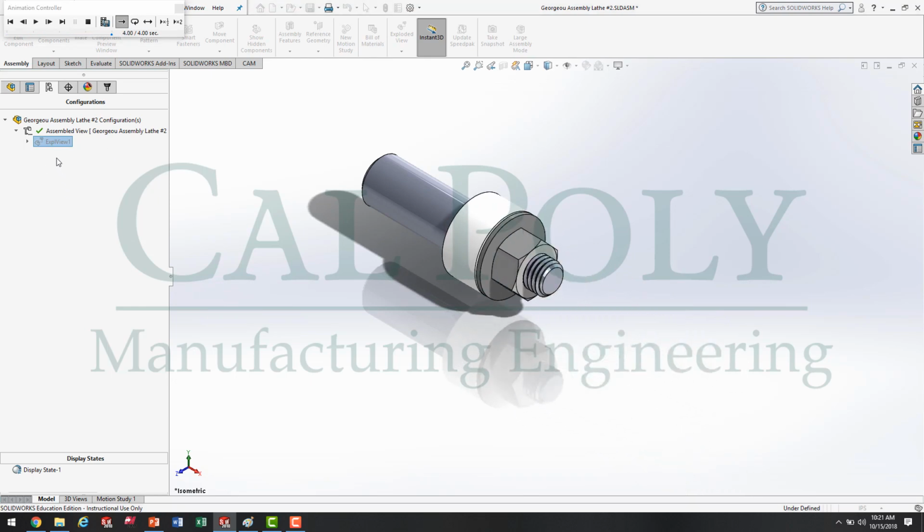So once you have an exploded view configuration down here, you're done with this step of the assembly environment. You can create as many exploded view configurations as you would like. We only need one for this assignment.